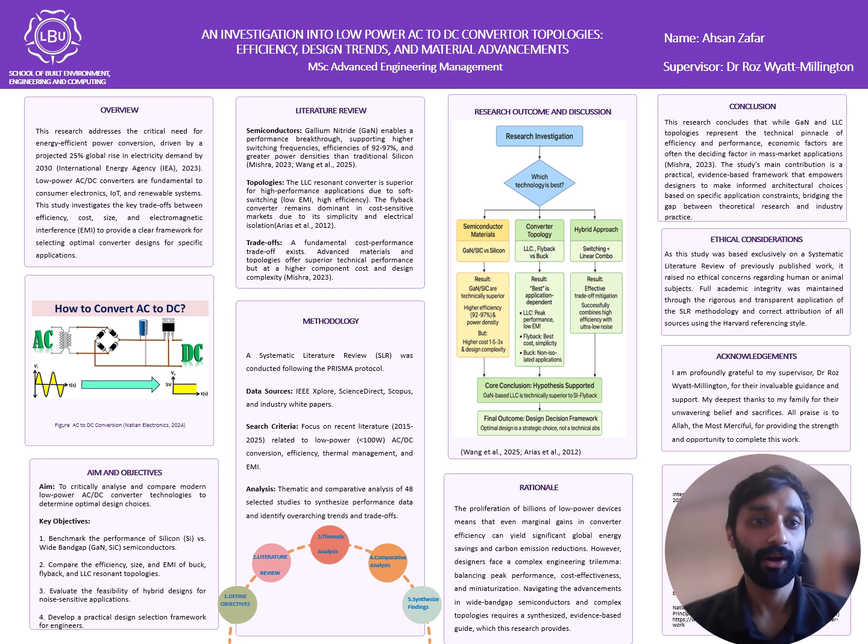Third, to evaluate cost effectiveness, checking if wide bandgap semiconductors like GaN and silicon carbide can be practical alternatives to silicon in real consumer products. And the last one was to propose a hybrid design, combining the high efficiency of switching converters with the low noise of linear converters, which can be very useful in sensitive applications such as medical devices and audio systems.